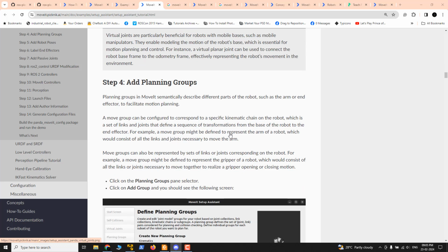You are asking whether we can get the joint angles in the program, right? Suppose I do a real robot. I have the hardware of that robot, and in the system I'm giving the goal position x, y, z, and getting the joint variables, so joint angles, theta 1 and theta 2 etc. And if I can directly apply the theta 1 and theta 2 to the real robot, I can achieve that.